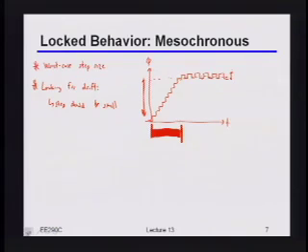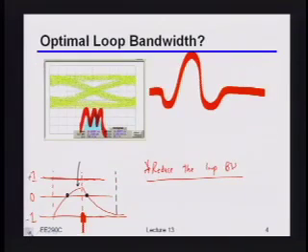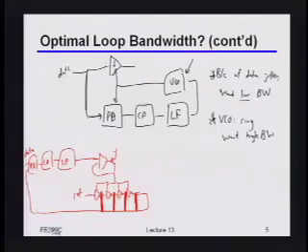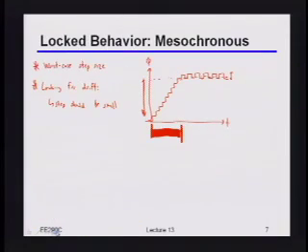And remember we said that, in terms of the CDR, I really don't want to be having anything with very high bandwidth because, no matter what I do, I can't really get things right in terms of the data jitter. So my best bet is to try and filter it out as much as I can, at least the things that are caused by SI, and then only track the really slowly varying components, where everything has been shifted statically, right? Okay, now, by the way, this is not to say that there are not many implications of making the step size small, and we're actually going to get into exactly what some of those issues are in 1 second, okay? Does that make sense? Or?